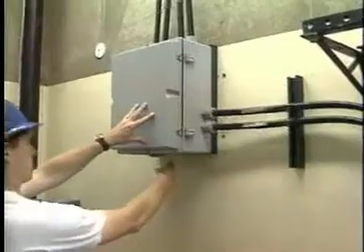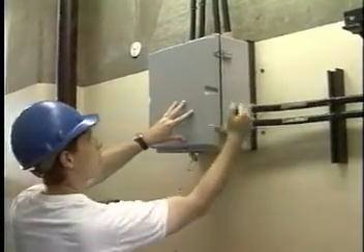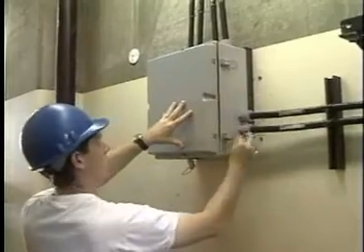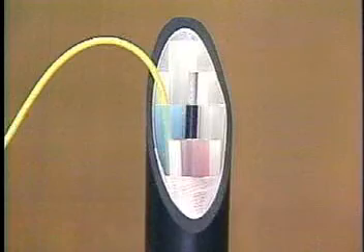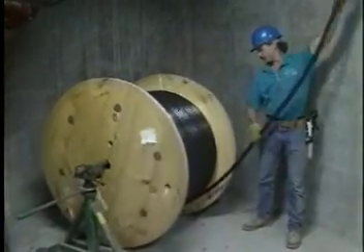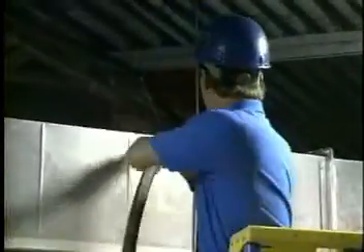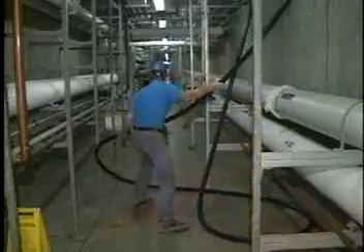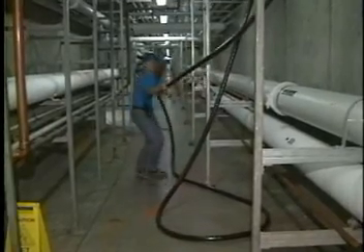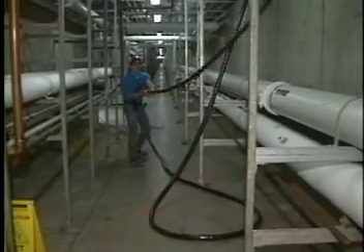A fast and efficient method of indoor fiber installation is the use of air-blown fiber, or ABF. A cable similar to inner duct containing a number of small plastic tubes is first installed along the planned route. Because the tube cable does not contain any fiber at this point, pulling tension and bend radius concerns are not as stringent, allowing easy and quick installation.